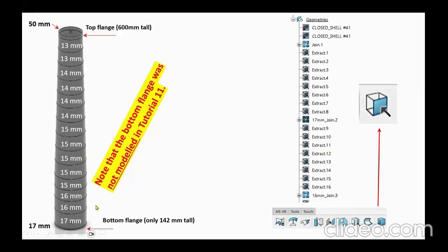So I will extract things which should have the same thickness, and then join them to get one piece that has that particular thickness, for example. And repeat that for all these thicknesses that you see here. And the extract icon in 3D experience is this thing that you have to go to the generative shape design and get the appropriate tab, which is surfaces, and you see that.